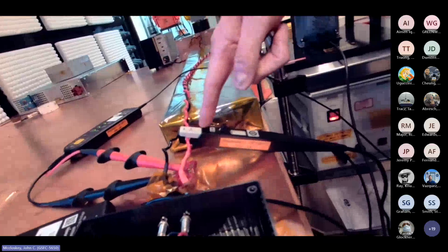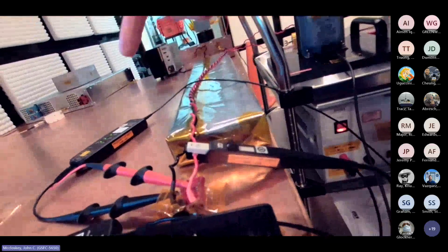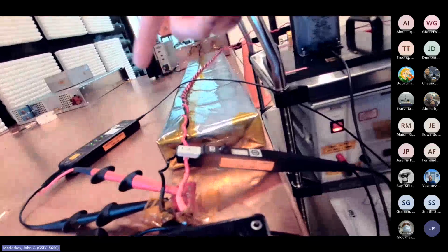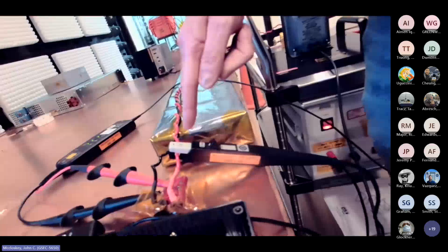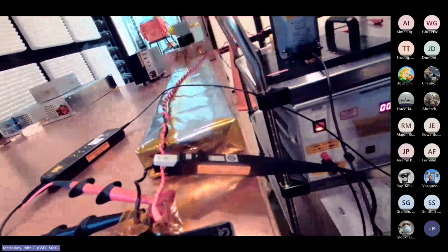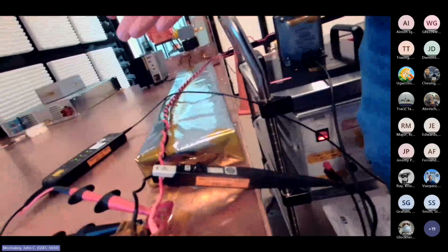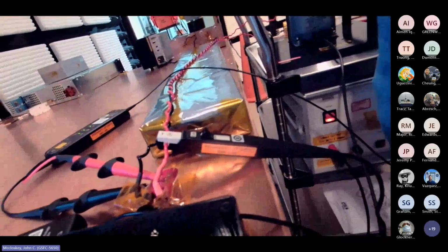Okay. But the best way to actually verify that you're not getting too much current into the EUT is to monitor it directly and incorporate it into your controller. So a voltage limit for CS101 is an incomplete limit. You must have a current limit one way or another, whether it's a direct current limit that you intend to monitor in real time and be part of your control loop, or do the pre-calibration step. One way or another, you have to specify that, or it's an incomplete limit.